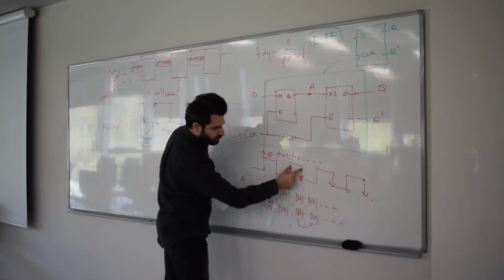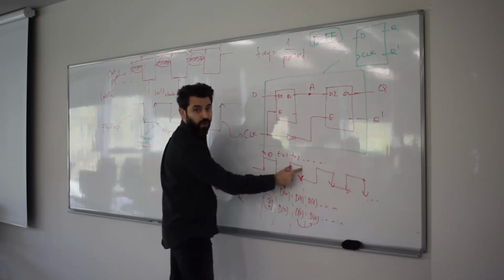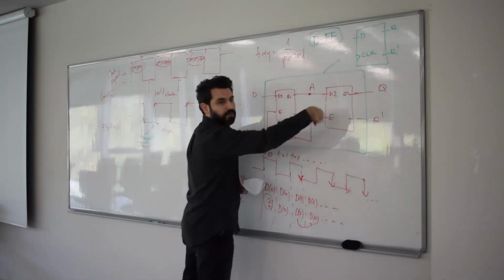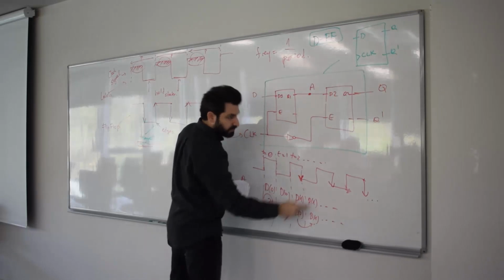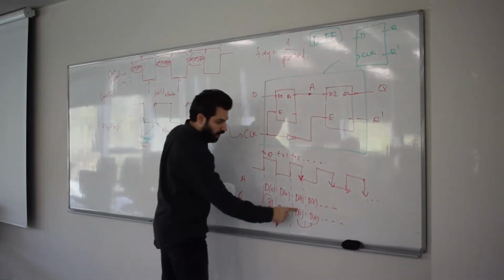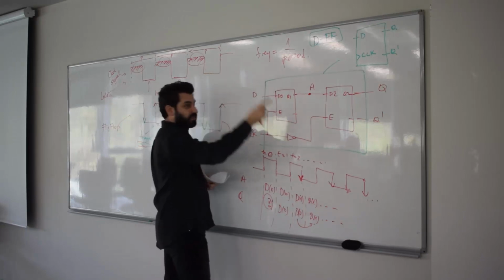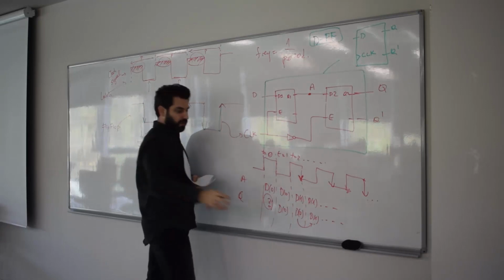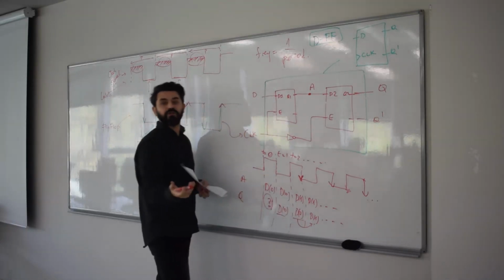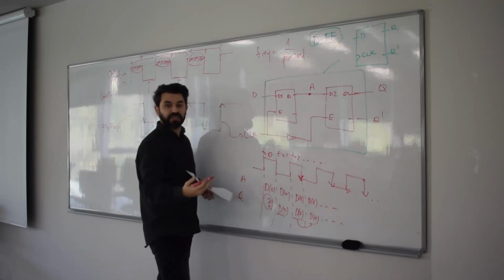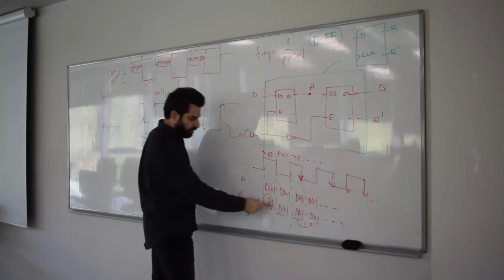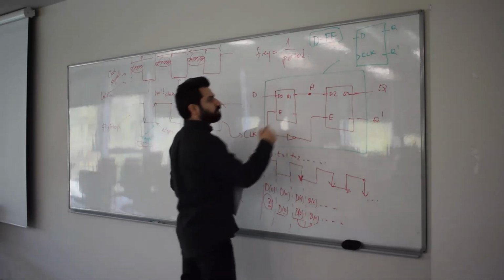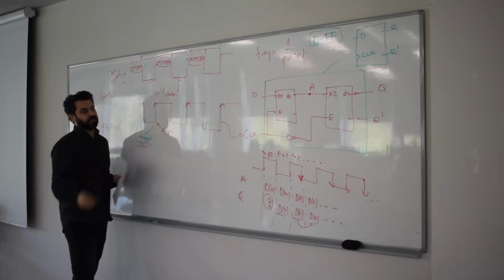It keeps D0 for as long as that clock signal is 1. Okay, you cannot copy D here because it already kept something here. It already holds on to something here, and that is the output of that hold value. That's why, unlike the D latch, it cannot copy the D input as is to the output. Okay, that's why these D0, these are fixed values. D0 is not like D(t). It's a specific value at time equals 0. So therefore, this is a falling edge or negatively triggered flip-flop.